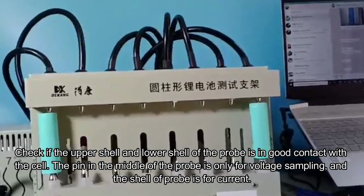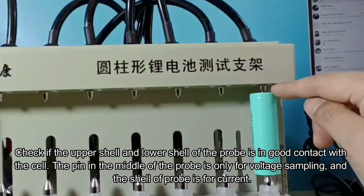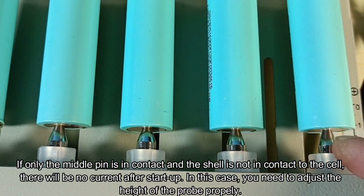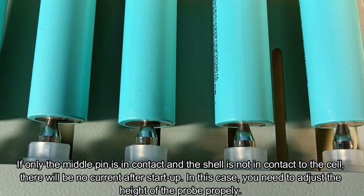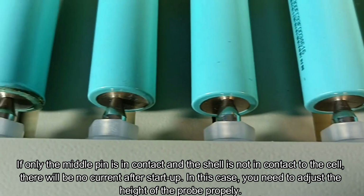Check if the upper shell and lower shell of the probe are in good contact with the cell. The pin in the middle of the probe is only for voltage sampling, and the shell of the probe is for current. If only the middle pin is in contact and the shell is not in contact with the cell, there will be no current after startup. In this case, you need to adjust the height of the probe properly.